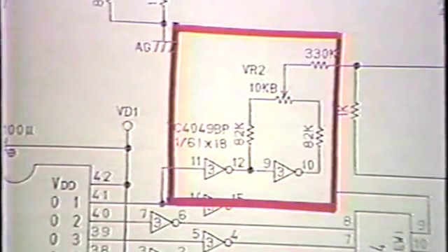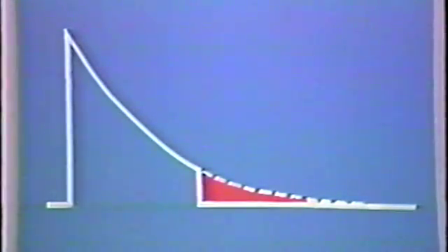Here, the O1 terminal is connected to the variable resistor through 2 inverters. Signals are sent to the other terminal of the variable resistor through only one inverter. Consequently, positive and negative O1 signals are applied to both sides of the variable resistor, so positive and negative O1 signals can be added to the digital to analog converter output by turning the variable resistor. A positive signal is applied when the sound decays quickly, and a negative signal is applied when a sound is unnecessarily prolonged to obtain the correct envelope. The above is the operation of the digital to analog block.